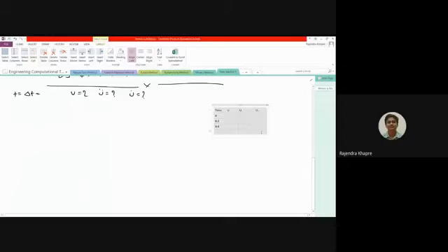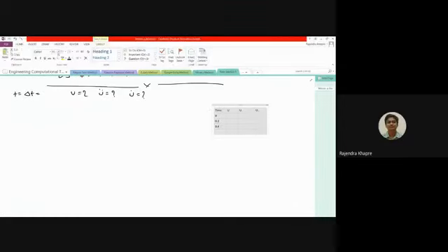Okay, fine. Right now what is available with us is the displacement, velocity and acceleration at t equal to 0. So this is 0, this is 0, and this is 2. We are interested in calculating these three values. For this purpose, we first have to calculate the effective load vector, that is, r will be calculated at theta times delta t location.